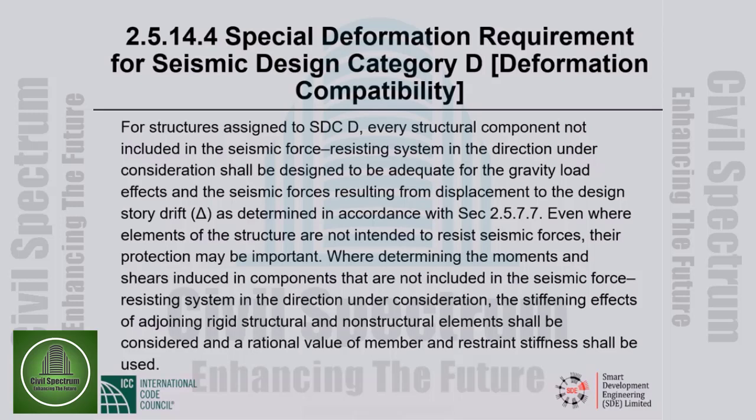The gravity frame is not part of the seismic force resisting system. We have to make sure that the gravity frames will continue to carry full factored gravity loads as they deform together with the seismic force resisting system, the shear walls, all the way up to the design earthquake displacements.